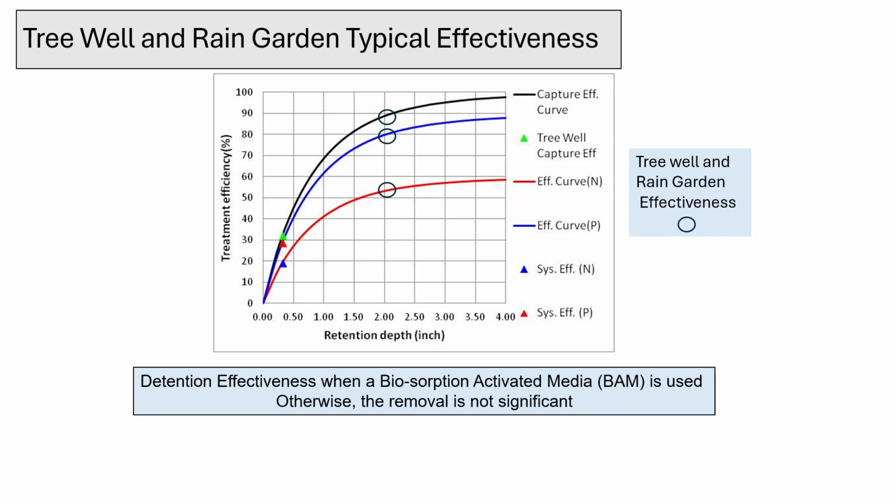In the specific case studied, the catchment area was 21,780 square feet, which is roughly half an acre. The volume dedicated to treatment storage was 3,630 cubic feet, achieved with an average storage depth of 4 feet across an area of 907 square feet. It's noteworthy that this treatment area constituted only about 4% of the total catchment area.